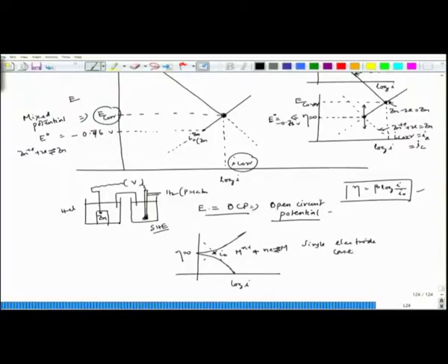But here we have two different reactions, it is not a single electrode reaction. One reaction is zinc dissolution, another one is hydrogen evolution, and this point would be the new set point, the way we have considered eta equal to 0 for the single electrode case. Now, if I do the same experiment, we will get a curve like this, and then the linear portion we have to consider and extend, and finally we will reach this point. This linear portion is achieved the way we have done for this case. It is the same way.